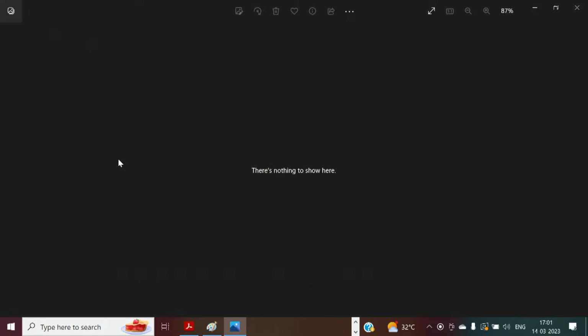Again, we have to load the content of R0 into the accumulator. For this one, we have to apply the command MOV A, @R0. This time the value at R0 is moved to the accumulator, and this value of the accumulator is moved to R2.